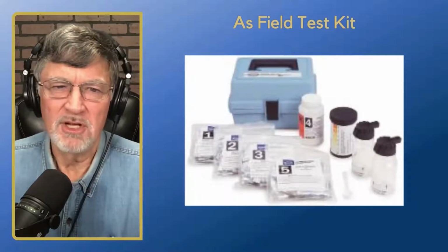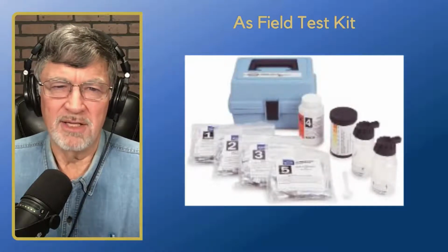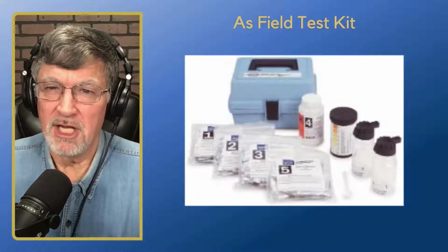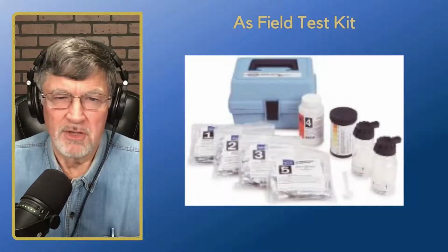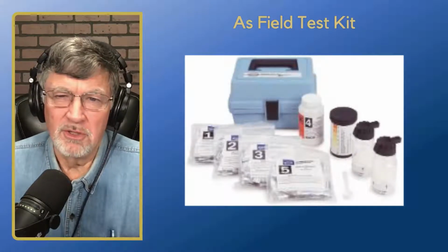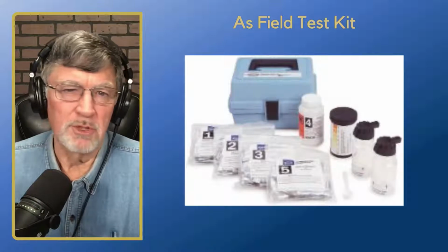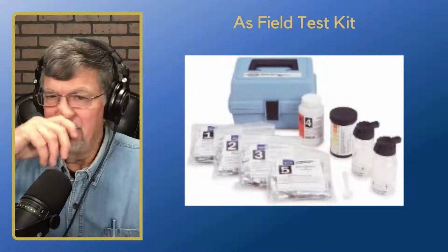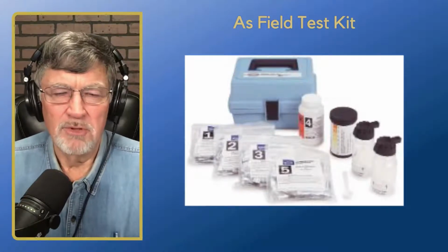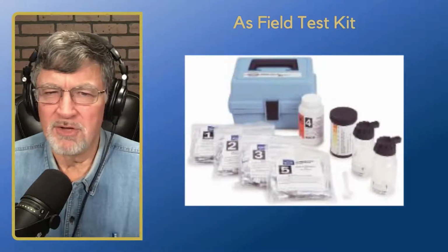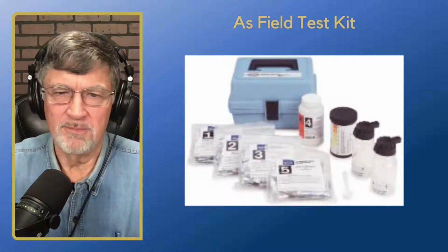It's not a certified lab test, but it's certainly something we can look at and use to do some screening in the field and help us make field decisions right then and there. So I would urge you to look at these. We've used these in the field a lot, and they can provide real-time, or near real-time, data. Arsenic takes about 12 minutes to run, so that's better than waiting, even with a quick turnaround time, 2 or 3 days to get samples back from the laboratory.